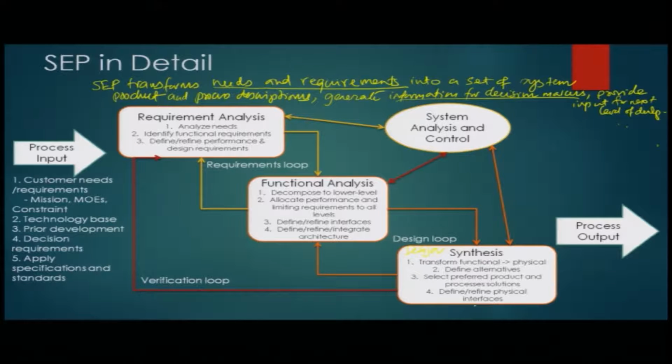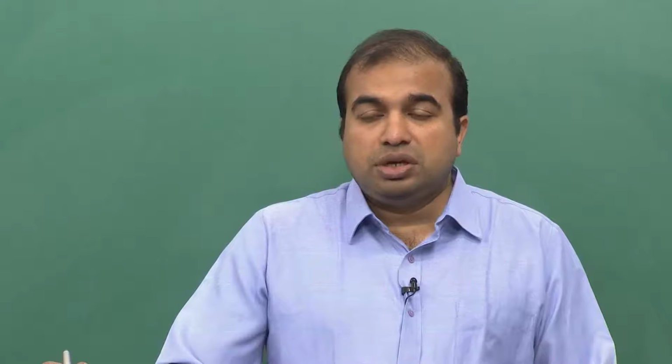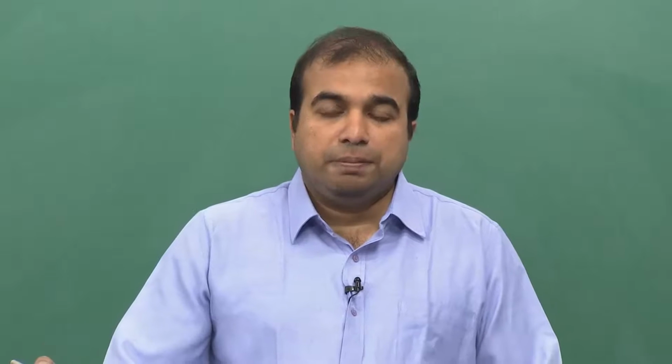So you would probably say that the UAV autopilot should interface with the electric motor, in which the input is how fast the motor should spin. The autopilot is a digital system which would give an input to the motor controller, and the motor controller will determine how to change the speed, the RPM, of the motor. So those interfaces, the interface between the autopilot and the motor controller and the motor controller and the motor, all those things need to be talked through and defined.